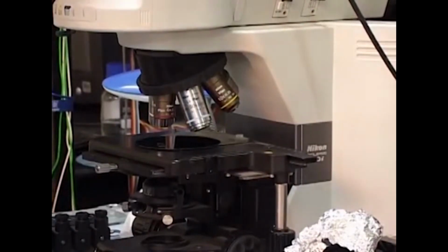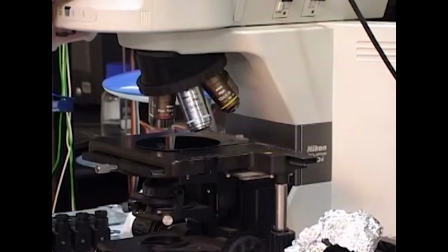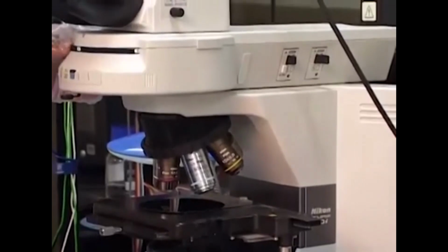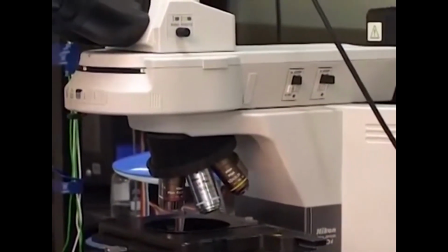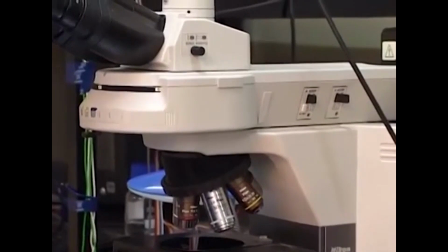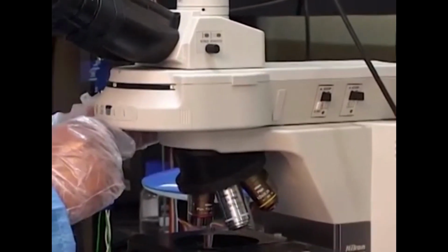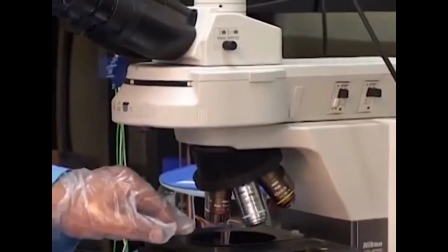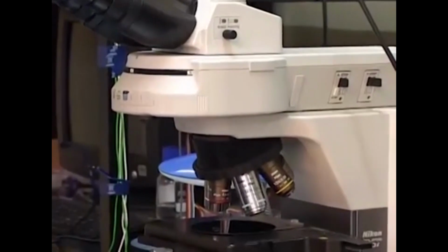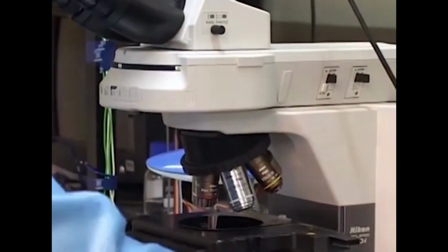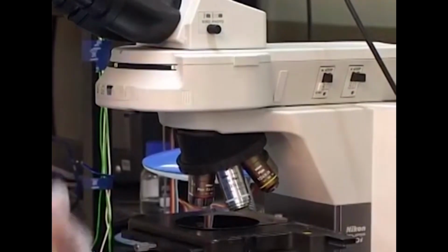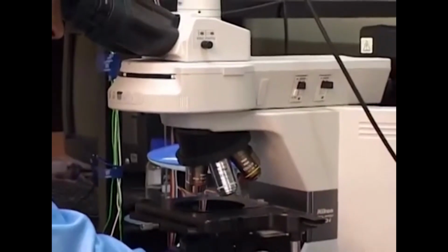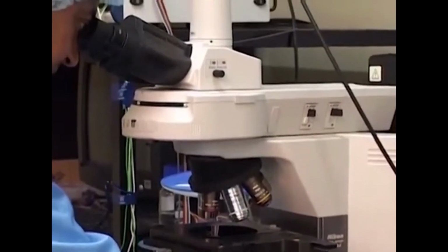But essentially now what I am going to do is to take this filter set to number 4 option, which is the bright field option here, and I already described what bright field would mean. Then I am going to turn on the shutter so that the light starts falling on the wafer surface through the 4x objective. My goal now is to look into the eyepiece and see how this image is being visualized on the top of this wafer, and yes, I can now see the images very cleanly which have come from the resist.